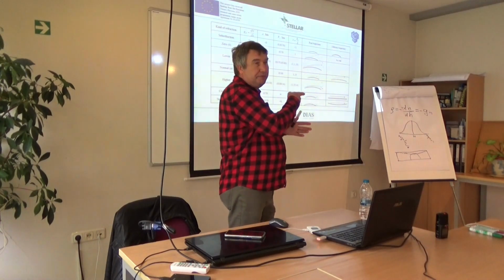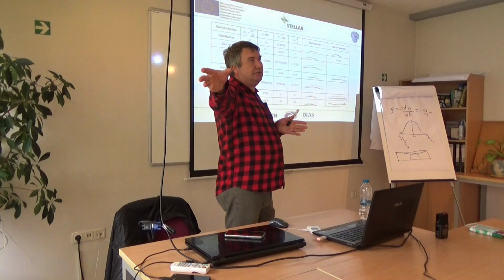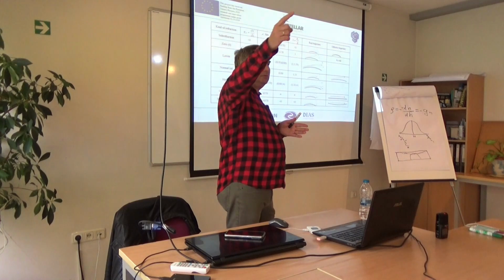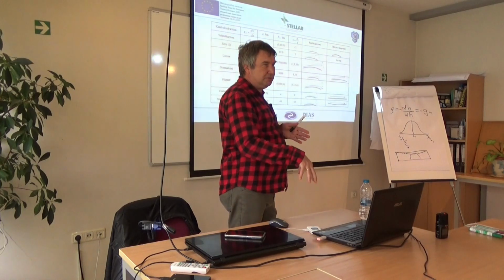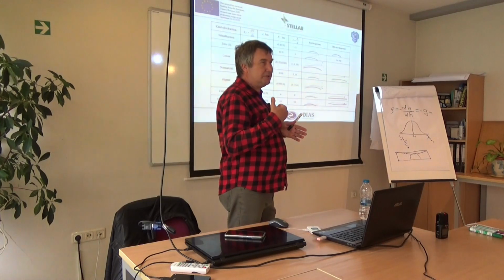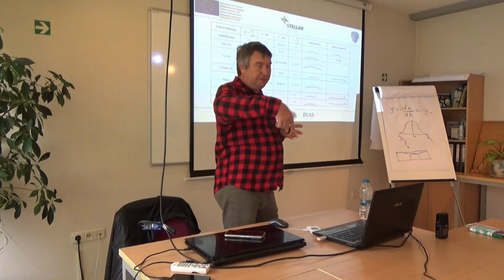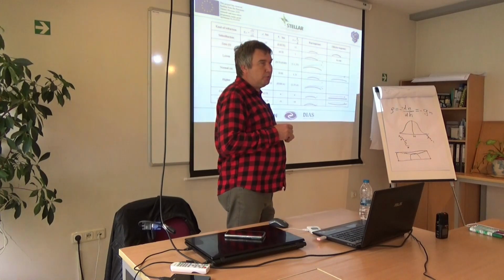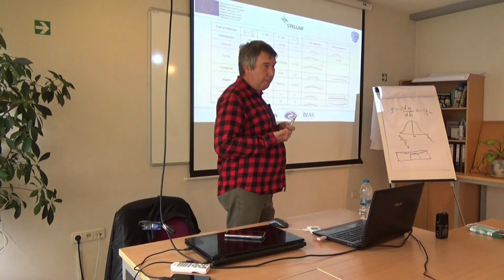But if we have super refraction, the radio waves from this transmitter that is at 100 kilometers will propagate to this place, and here we will receive signal from the transmitter that we want to listen, and from the other one that is with a different working area. And this is a problem with electromagnetic compatibility. So super refraction leads to this.